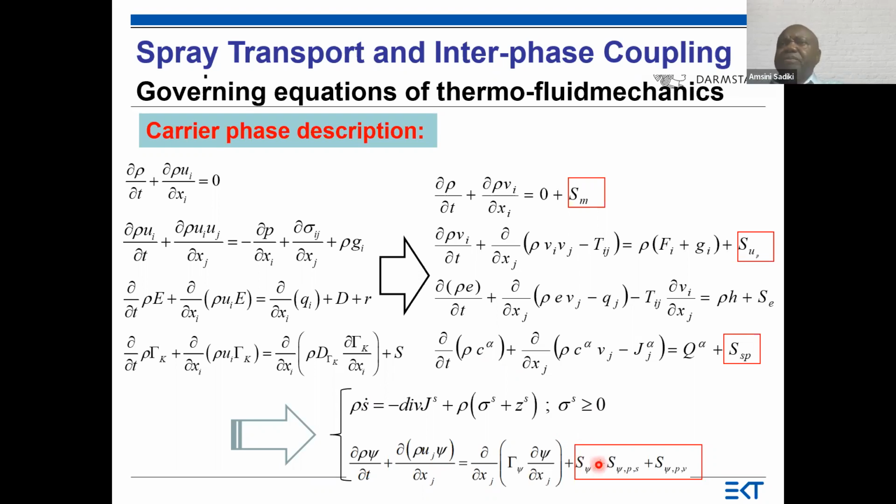But in this term, which is a generic term, we have different sources. We have the classical source term here, which considers the non-convective contribution, the non-convective diffusion term, like the Cauchy stress tensor, this one here, and the scalar flux.